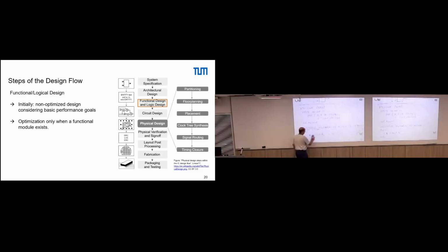Questions so far? So, what we have now is this kind of a description. If you're done with that, what would you do? Well, since you never worked with RTL, with hardware description, you most likely also never built a circuit. So the next step is we now synthesize this into a gate level, transistor level netlist. For this synthesis, you have to provide some inputs and some additional data, and so on and so forth. But this synthesis effectively is done by the tools themselves.